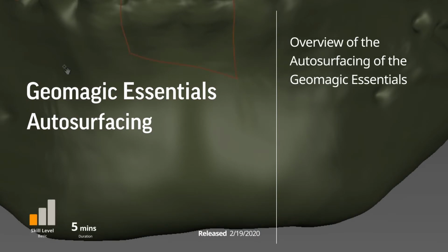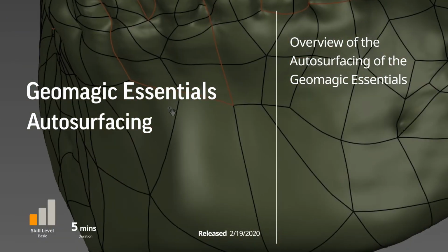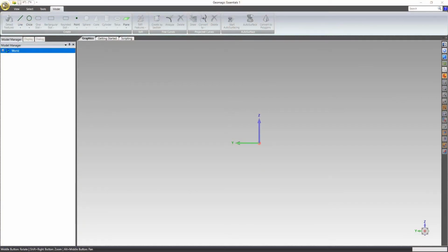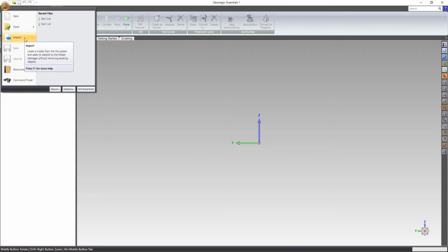Today we will be going over how to prepare and auto-surface a model in Geomagic Essentials. To start, let's import a scanned model. I will do this by coming up to the 3D Systems logo button, then selecting Import.